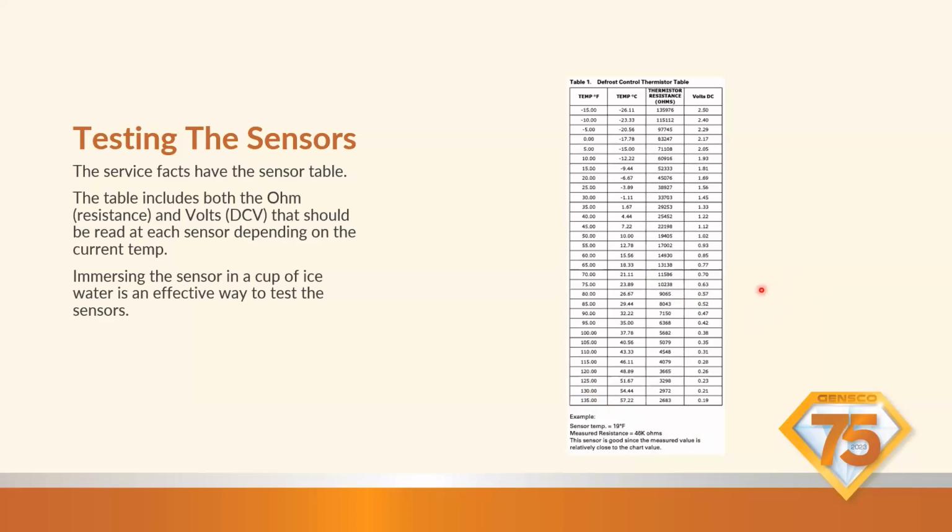So when you're trying to test these sensors, make sure they're reading accurately. One of the most common things we ask people to do to make sure that they're very accurate is you disconnect the sensor from where it is, and you submerge it in a cup of ice water. Who carries ice water with them? Not many people. Most homeowners are willing to lend you some water and some ice if they have it, and you can test those sensors in 32-degree water. As long as your water has ice and water in it and it's stirred, you're going to have 32-degree water.